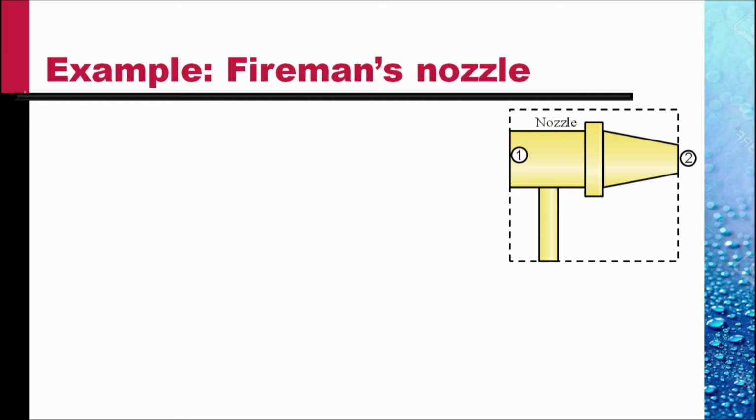This is the control volume that we take. We draw all the external forces on this. There are only two: the gauge pressure P1, and the force Fx. There is atmospheric pressure all around, but atmospheric pressure all around leads to zero force. A uniform pressure all around a volume leads to zero net force.